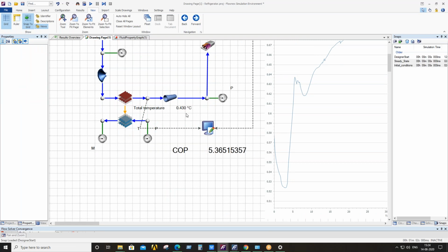Secondly, you told in the previous slide that the dryness fraction is 1.04 and 1.01. That cannot be possible, because it is a maximum of 1. The dryness fraction will remain only between 0 and 1. It can't be more than one, even theoretically or practically. No, no, I am not telling about that. Let me explain.